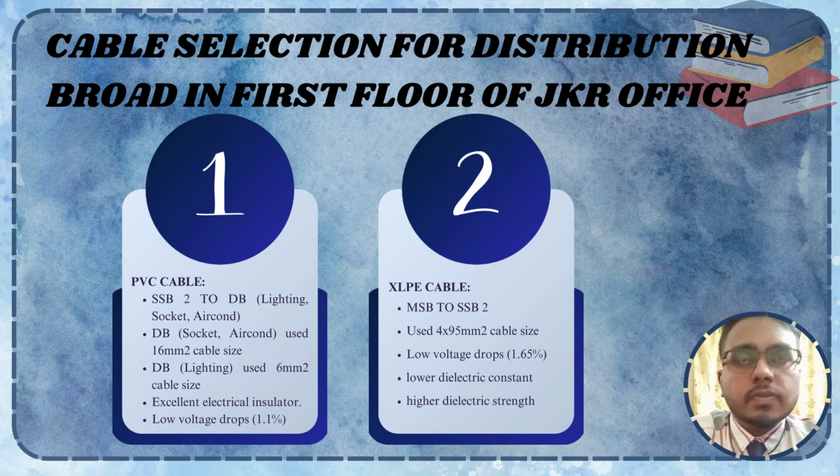Elasticity to wire, which facilitates handling and installation. This is especially useful for conduits where the wire may be bent and tucked through with ease without causing any damage to the installation. Furthermore, both PVC and XLPE's fire retardant qualities enhance safety. When burnt, XLPE produces no harmful emission, and PVC is naturally fire resistant and self-extinguishing, which lowers the possibilities of fire spreading in the event of an electrical malfunction.